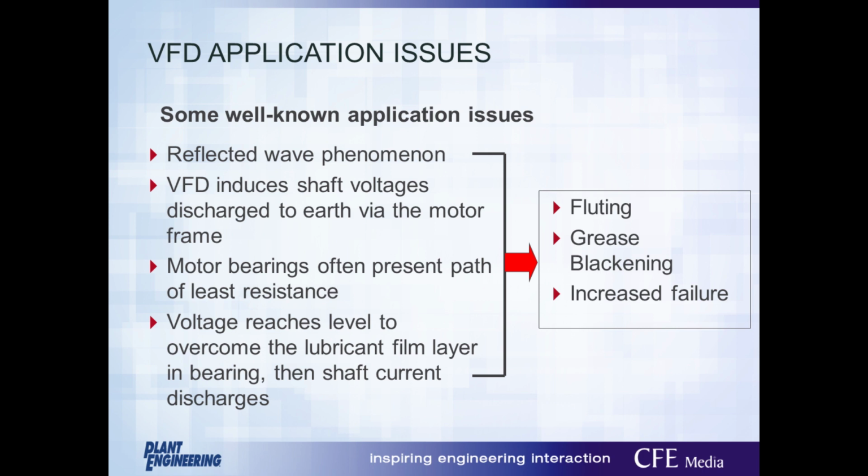There are some disadvantages. I would like to spend a few minutes going over the issues and what you can do to mitigate those. Some well-known application issues include the reflected wave, which we'll get into more in a minute, and bearing effects, including fluting, grease blackening, and potential increased motor failures.